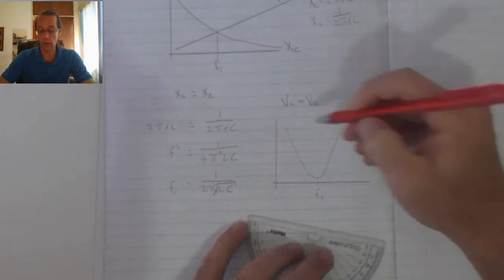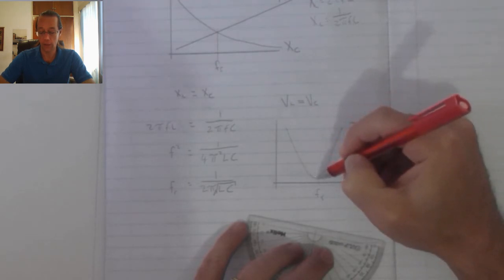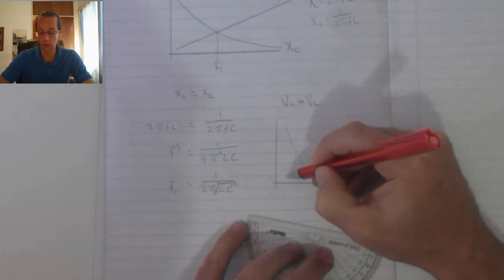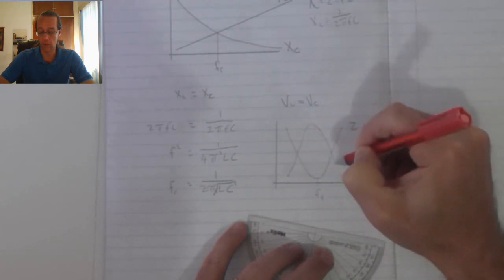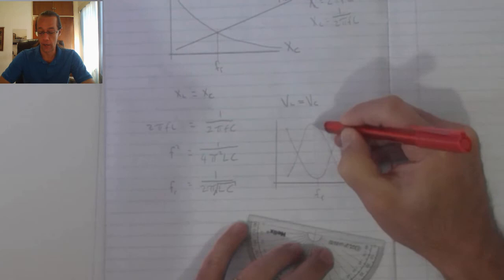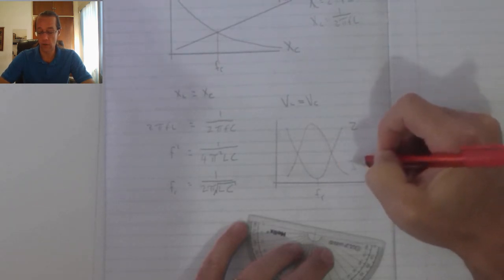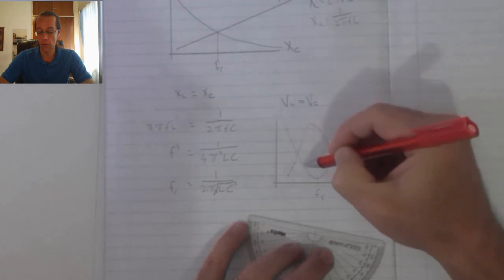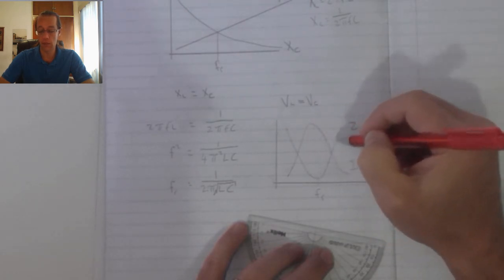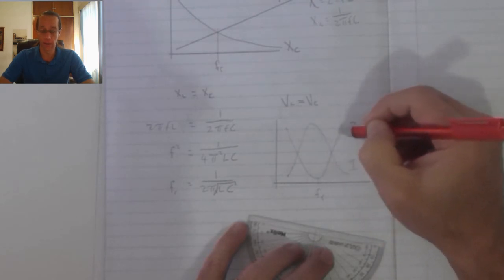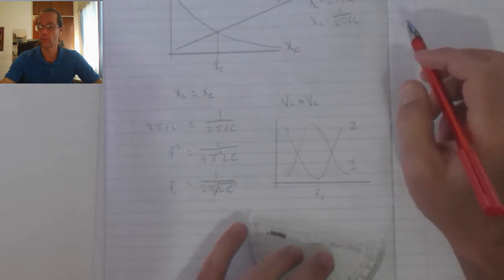But because my impedance is decreasing the closer I get to resonance, I will get an increase in the amount of current around that same resonant frequency. So as my current increases, it means I'm moving closer to resonance. As I move away from the resonance, my impedance increases, and as a result my current will decrease.